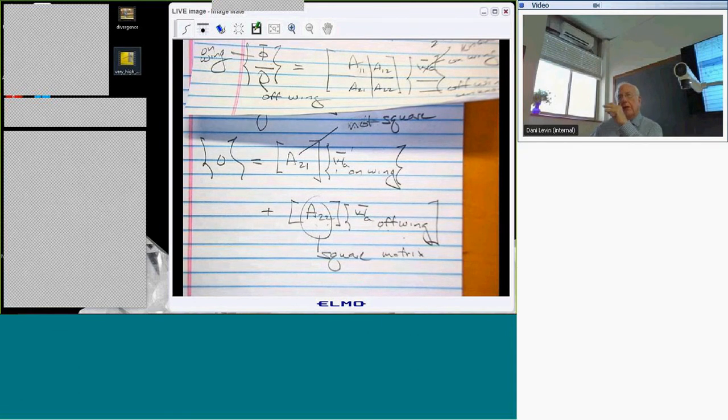Now, if you watch closely, that violates all those conditions I was talking about. I was using the continuity argument to show that the pressure perturbation is zero off the wing, which is in fact the condition we use to work out these solutions. But then there can be a jump from zero to infinity as I go onto the leading edge. What's remarkable, first of all, is that it's a weak singularity. So if I take that pressure distribution that goes to infinity and integrate it to get lift or moment or any generalized force multiplied by mode shape, I get a finite number. You'll be happy to know that.